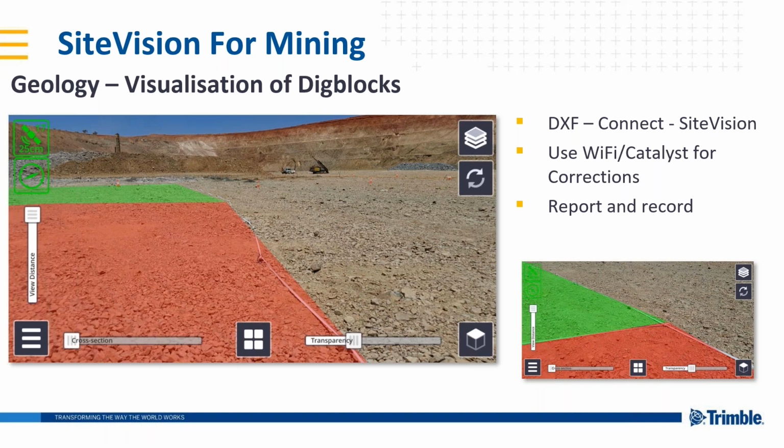What we found here was that, in terms of accuracy, it's not as crucial in a mining environment to have centimeter level accuracy. Down in the pit, using the Trimble Catalyst functionality of the device, the corrections we were getting were sufficient, achieving plenty of satellites. You can see in the big picture we have 17 satellites, and at that point we had an accuracy of 25 cm, but we did get down below 5 centimeters in the pit, which was quite a good achievement.